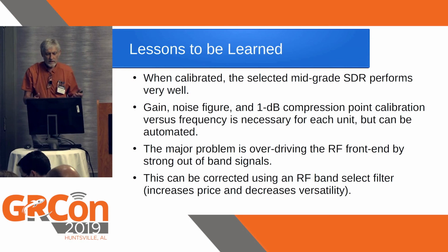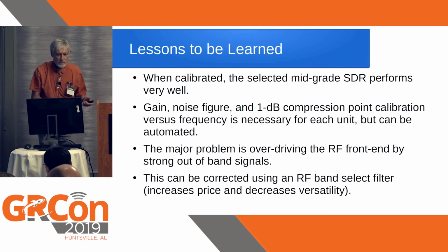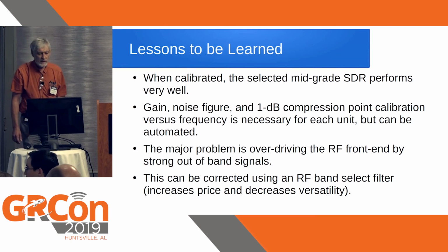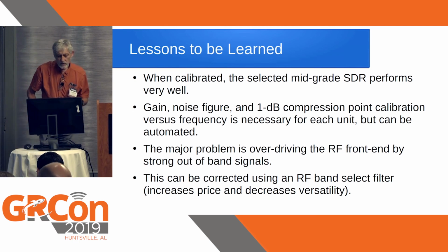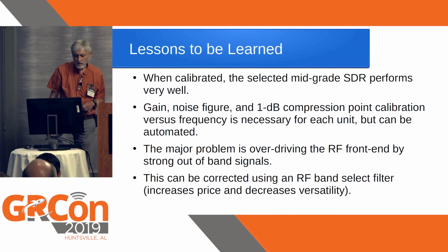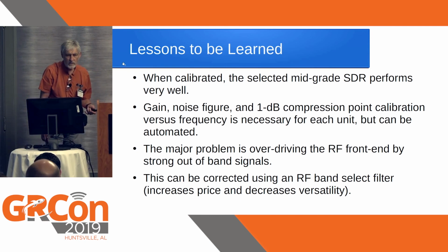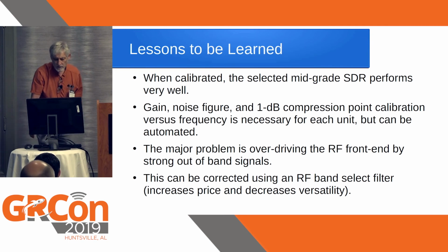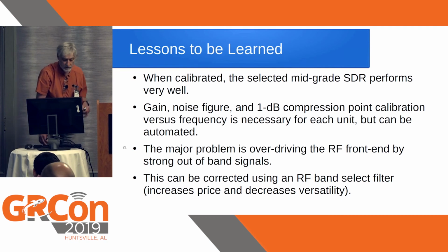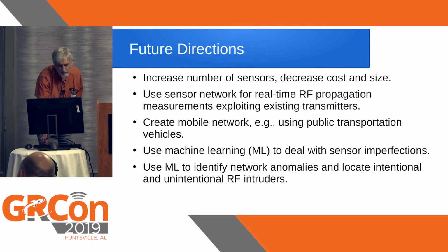And in a regular spectrum analyzer, you have plenty of filters and stuff in there that you can switch in order to avoid that. And you usually also have a larger dynamic range. With a software-defined radio, you don't have enough dynamic range, and you don't have any protection of the input for out-of-band signals. So you actually have to put that there yourself, and you just have to be aware of that. Once you do that, then it actually works quite well.